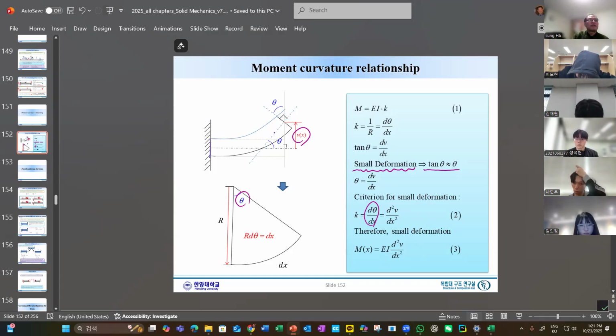Again, before deformation, this is nothing new, okay? But I just like to emphasize this was the beam before deformations. And now, for convenience, let's assume that on the left-hand side we apply the load. And now this is going to have a deflection, which we're going to calculate right now, denoted by v(x). So we only pay attention to the neutral axis.